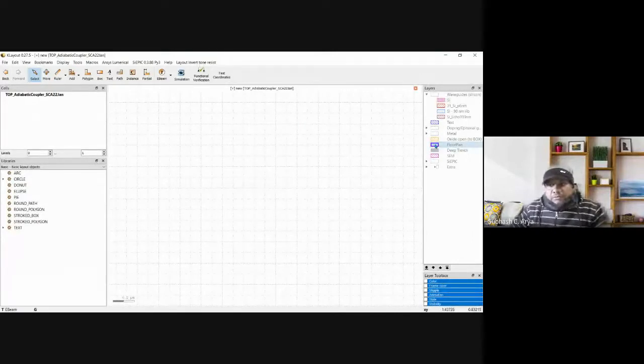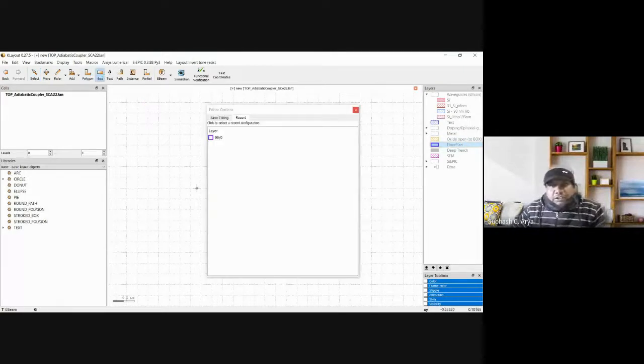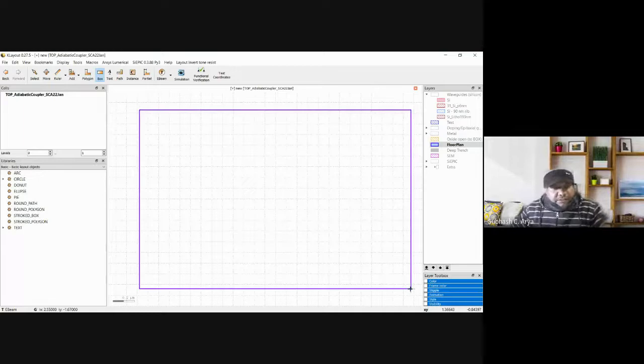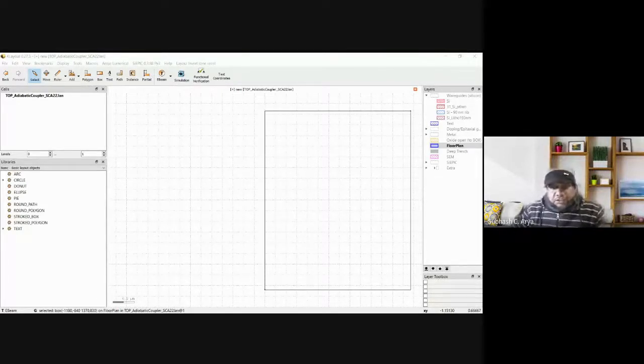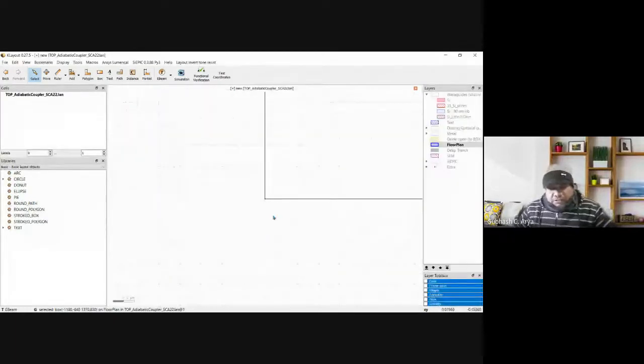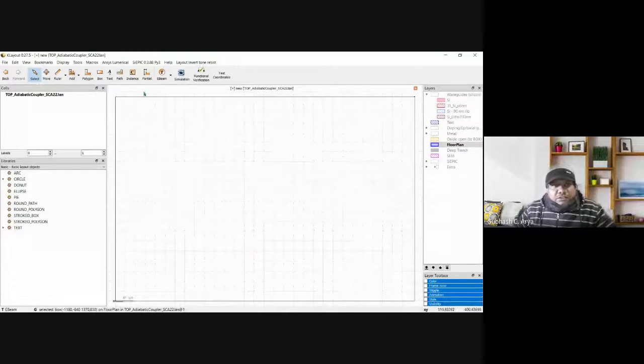So start from the floor plan, on the left right-hand side, this floor, go to box, select this box, draw a box of arbitrary size, click outside, skip, click here, press Q to select or edit the box properties. So left corner, x is equal to 0, y is equal to 0, and 605 micrometer, we are taking standard values, and here 410 for y. So x is 605 and y is 410. Press F, so it is in the center.